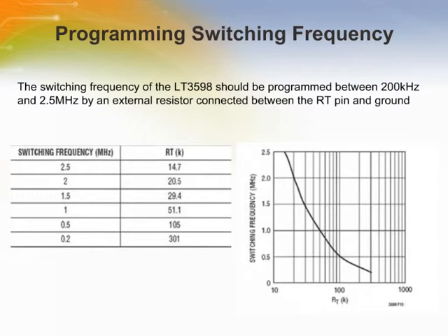Selecting the optimum switching frequency depends on several factors. Inductor size is reduced with higher frequency, but efficiency drops slightly due to higher switching losses. In addition, some applications require very high duty cycles to drive a large number of LEDs from a low supply. Low switching frequency allows a greater operating duty cycle and hence a greater number of LEDs to be driven.